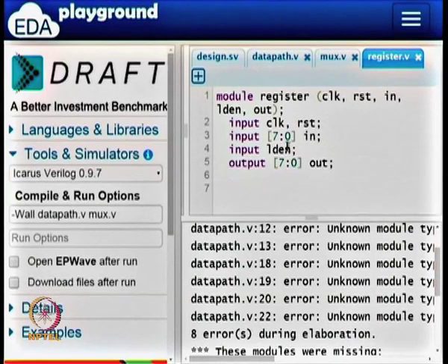We have that, and once we are done, what we need is to specify a bunch of things. What do we need? We need to specify that the register, on either reset or on load, is supposed to do different things. And we decided that the whole thing will be a synchronous circuit. So there is nothing which is going to be asynchronous.